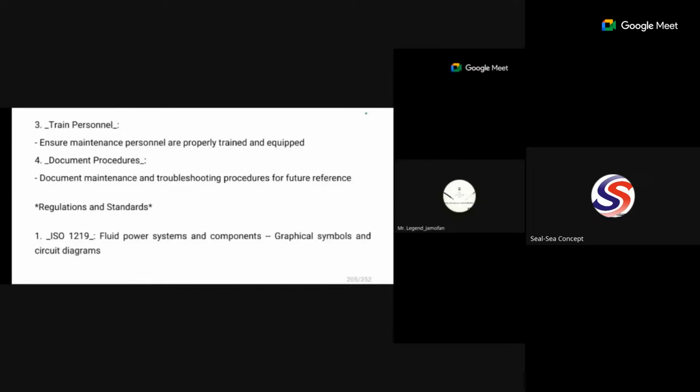Like in our last class, my friend here shared his experience about how they take LOTO at their place of work. So you can see that is proper documentation. Everybody knows. Everybody already has a LOTO tag. They can take group LOTO to go and perform maintenance, like more than one department performing maintenance on a particular system at the same time. So these things are documented.